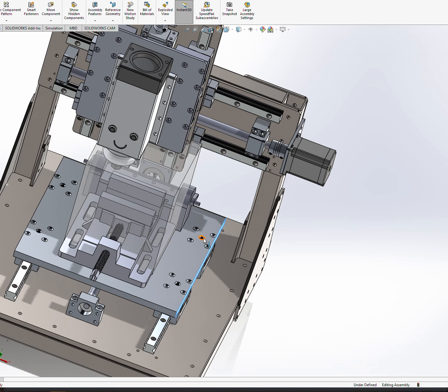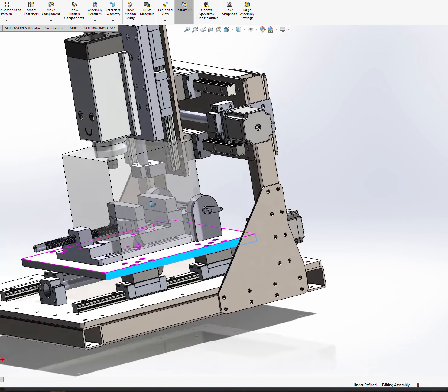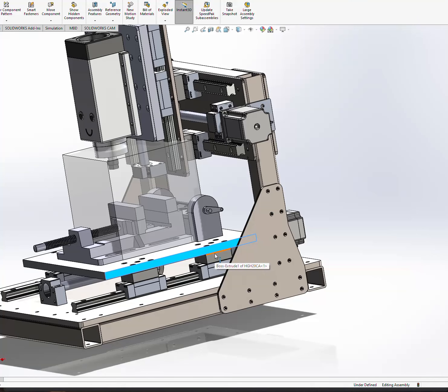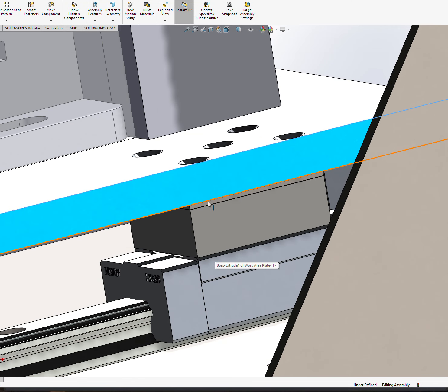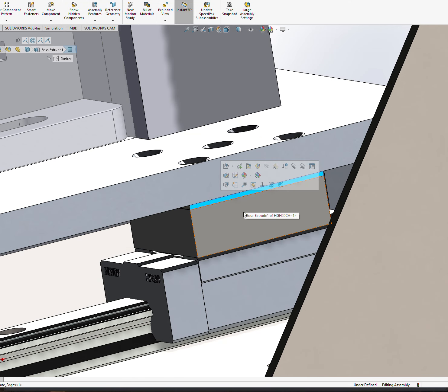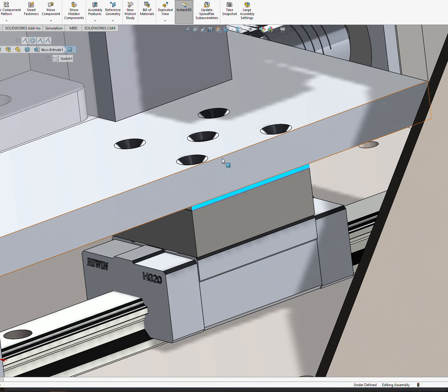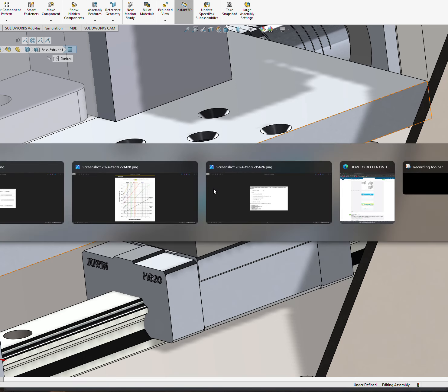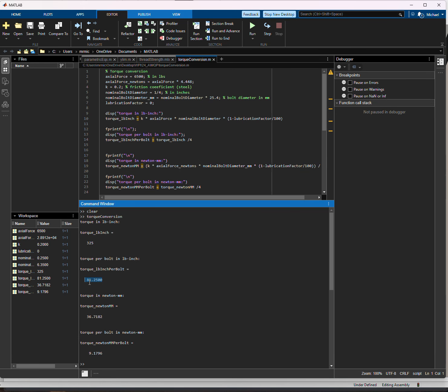Now, the set screw is also going to be going down beneath this and pressing against this steel barrier that I put right here to lift this plate up slightly. When that happens, the set screw is no longer engaged, and the full 3/8 helical that is going to be inserted in this 1/2 inch thick plate will be slightly less. So I decided to cut the value of 80 down to 50 inch-pounds per bolt to be on the safe side because we don't want this to rip out. So let's say we max out the torque at 50.